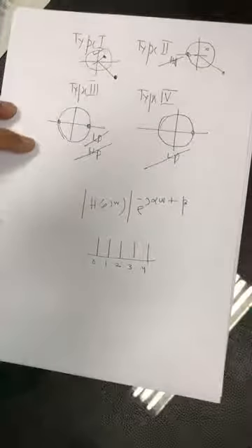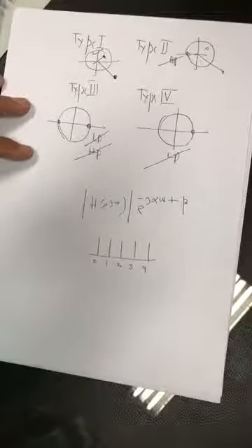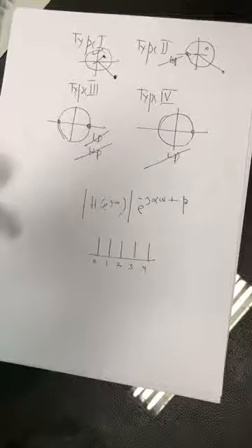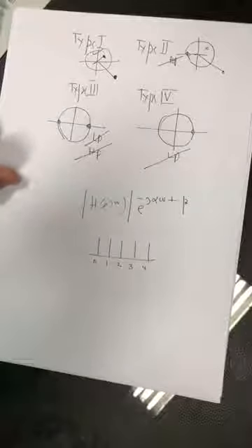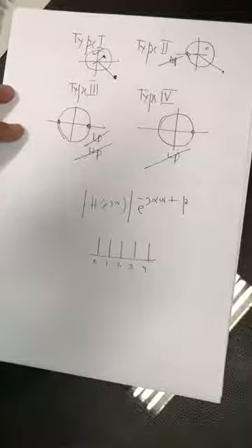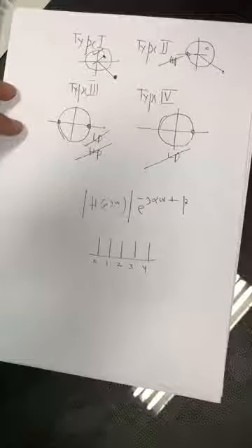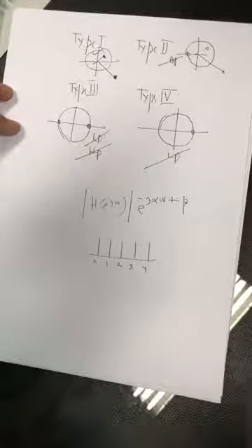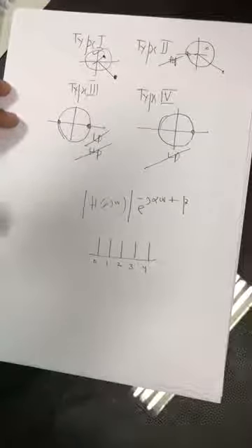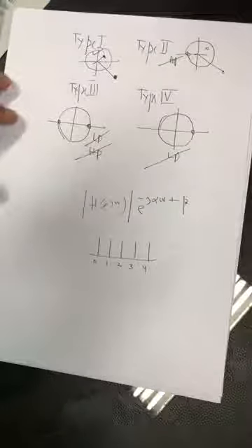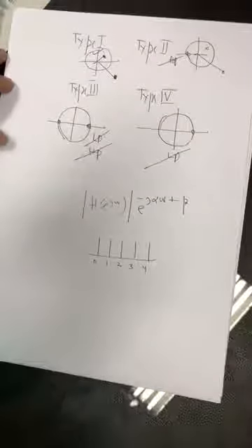Okay, and I can ask you a question. Obviously, which type of linear phase FIR filter is it, and obviously you can just give an answer that what cluster of 4 zeros play in the frequency we want to pass. The frequencies you want to pass, cluster of zeros will let those frequencies pass. Okay, and we are not ourselves placing them. The MATLAB toolbox is placing the clusters of zeros in those frequencies which we want to pass.